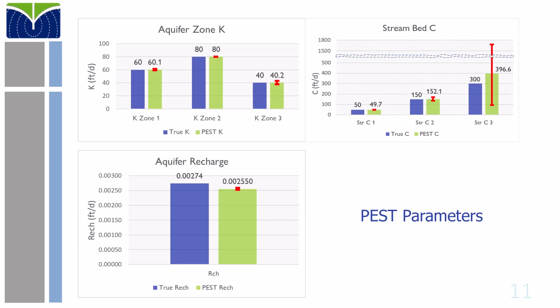So I thought about how I might be able to provide PEST with more information to let it better estimate streambed conductance. We already know the stream stage. It is the reference head values in the AEM model river elements. So I thought that installing piezometers next to the stream to measure aquifer head beneath each stream segment, and also measuring the stream flow in each segment, might help PEST estimate the resistance of the streambed material in between.